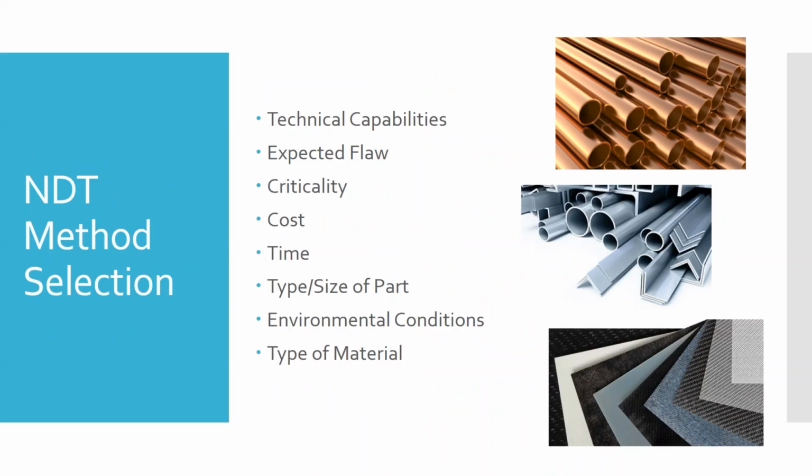Environmental conditions. Some things can be done in bad weather or outdoors, other things can't. Some things are temperature sensitive, time sensitive, others are not. If you're trying to do thermography, which is infrared imaging, you can't do it on a bright sunny day because all you'll get is the heat of the sun reflecting off of all your surfaces. It'll wash out any ability to see what's going on in the part.